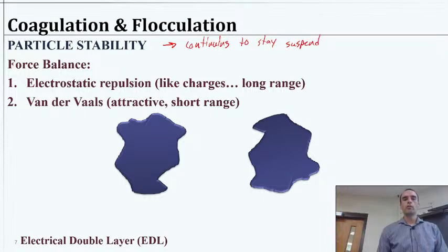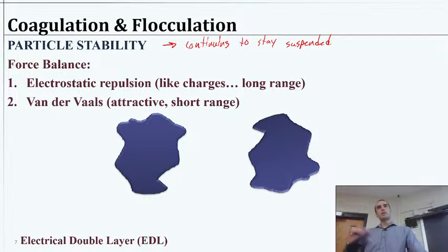So suspended particles are similar to something that's dissolved. They're just floating around in the water, but they're not actually dissolved because it's a solid, right? So the colloids, you might hear as a term, or these small particles that are stable, are an interesting in-between point between some solid thing and something that's dissolved. Okay, so then if we destabilize the particles, that means we've removed their little force fields and allowed them to